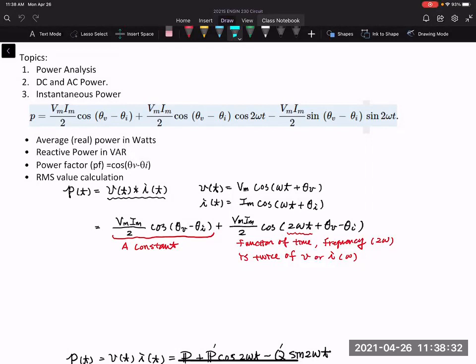But it's not the whole story. That power is actually not the power for just a resistor. If you talk about the power in the circuit, and if you have not only a resistor, but also a capacitor and inductor, they also have power. Then how do we represent the power of those things? Well, since everything in the phasor is represented by a complex number, power can also be represented as a complex number as well.